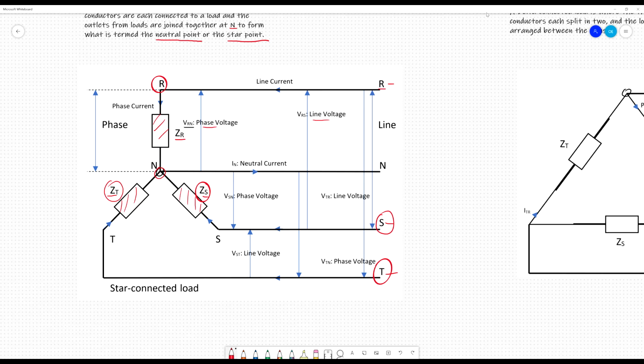When we specify a voltage, say 440 volts, two things. One, that's the root mean square value. So it's effectively the average voltage, because don't forget the voltage is constantly changing in a sinusoidal form. So if we flip that voltage up, we get the RMS, which is approximately there. So although it's completely changing all the time, we refer to it by 440 volts RMS. So it's going to be the line voltage. It's going to be the voltage between any two phases.